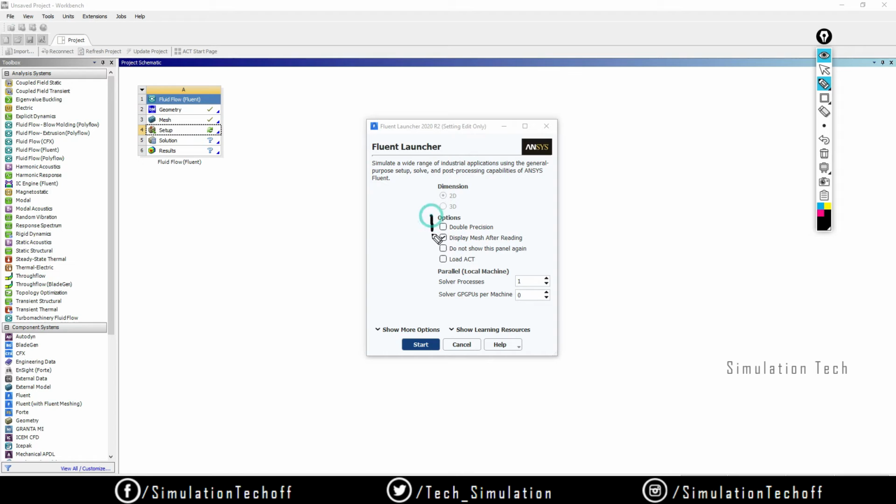And there is another option that is called double precision. If you just enable this option, your problem's convergence level will increase. Okay, so there is a higher probability that your problem will converge. Also, the solving time will be a little bit higher than in normal cases, but usually we enable this option for a complicated problem. For this problem, maybe you can enable or disable this option.